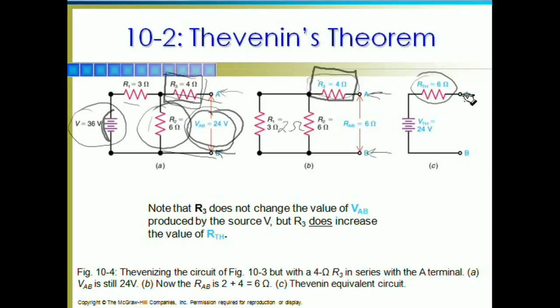And once again, we can throw that 2 ohm resistor back in here, and we'll find that it is approximately 1/4. In this case, it's 1/4 of the total resistance. So 24 divided by 4, 6 volts, 12 amps.